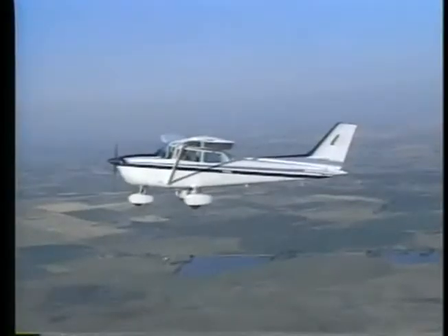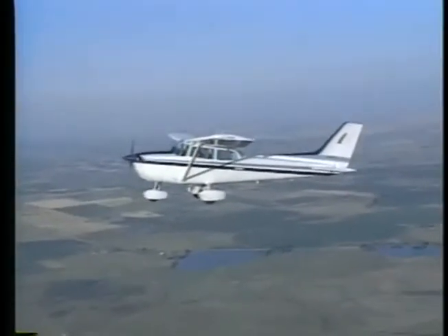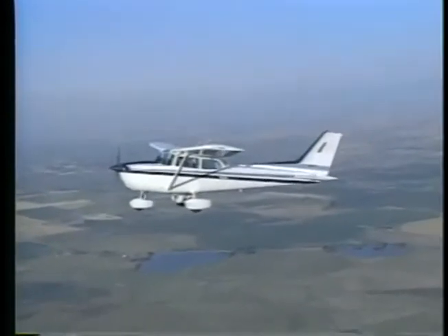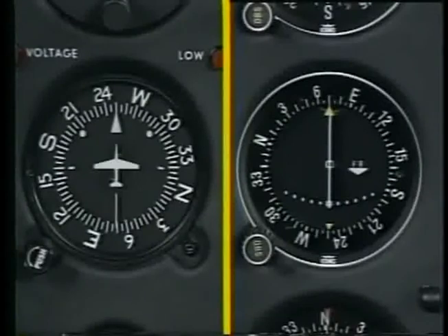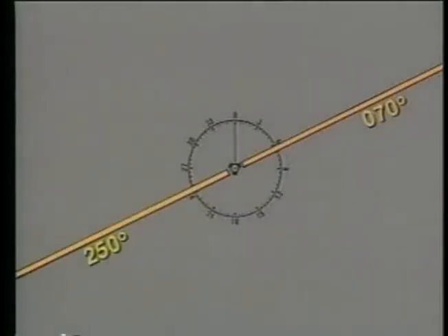Although VOR navigation is quite simple, you should be aware of a few unique factors, such as reverse sensing. This happens when you select and fly on a radial that is 180 degrees from your heading. When this occurs, the information provided by the VOR is opposite the normal indications. For example, to track to a station on the 070-degree radial, you need to set 250 in the course selector, then fly a heading of 250 degrees.